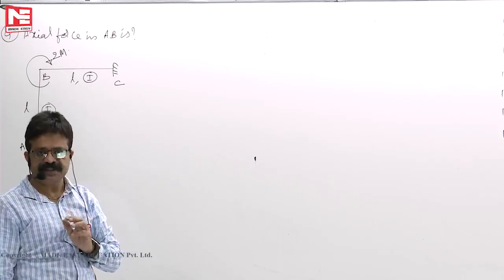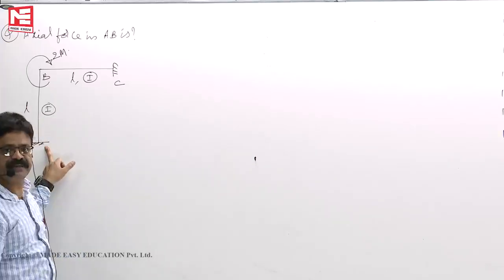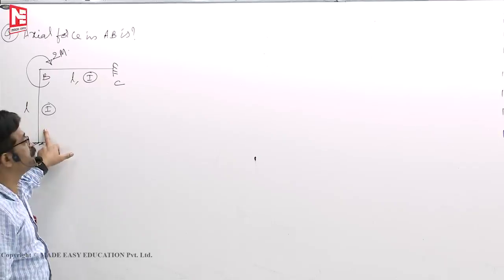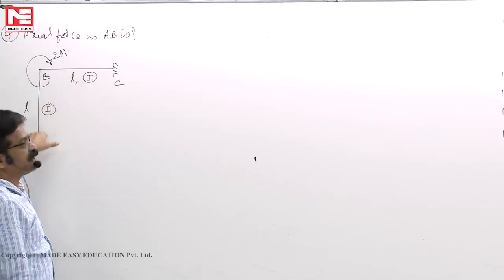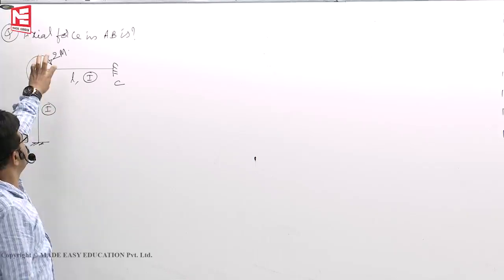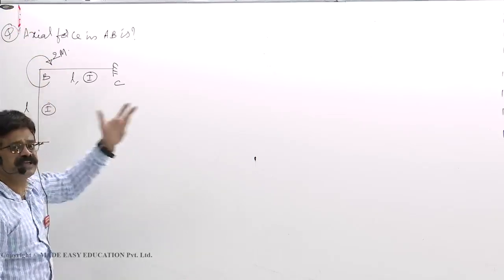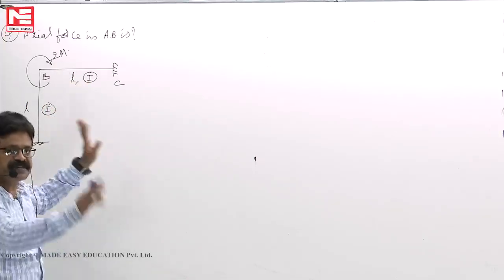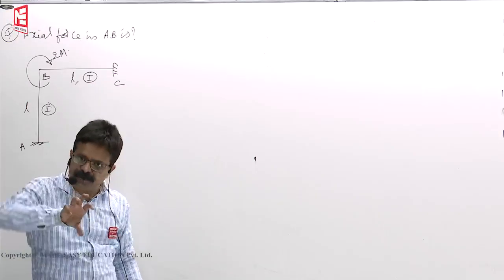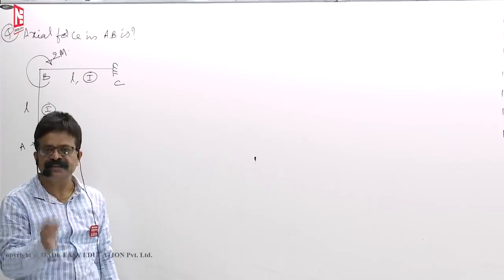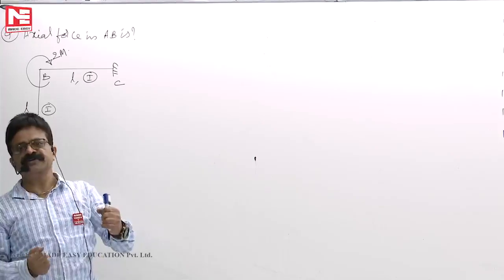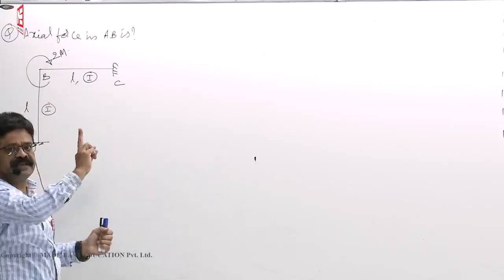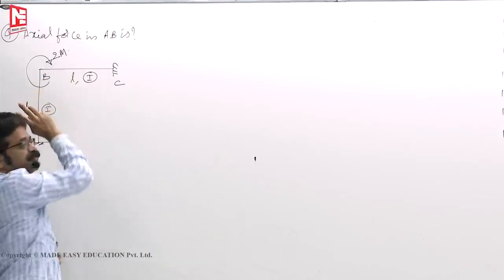Next, second step, distribution factors. This is the footing, member. Footing I told you 1, member 0. So 1, 0. At B, same strengths. So if at all you apply some moment, both members will share the moment equally, 0.5, 0.5. But here, entire moment is taken by the support only. On this support, if you apply 1000 kilonewton meter, nothing goes to the column. Entire thing, support only will resist and take and keep quiet. But whereas if you apply at B, both will share because distribution factors are 0.5, 0.5.